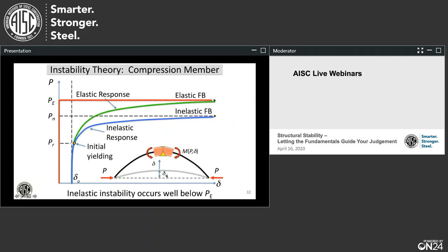It has a small initial imperfection, or there is some eccentricity in the load or some combination of the two. At first, you start applying the load, and really not much. You get maybe a little lateral displacement, but then as we put more and more load on, the bending starts to increase and dominate the problem, and we get a lot of bending followed by a lot of deflection, and if we're modeling yielding, we'll get a lot of yielding, and we can either simulate the elastic flexural buckling load of the column or the inelastic flexural buckling load. So again, two schools here.